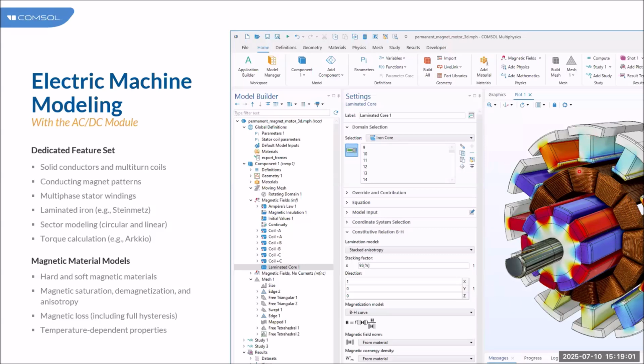we can define these coils as multi-turn coils with a particular conductivity, as well as how much insulation thickness is involved, so that we will be able to give the stacking factor of these coils. And these are placed in the stator slots as you are seeing here, which will be made of laminated cores. Both this portion of the stator slots, as well as some of the inside part, will be made of laminated cores.